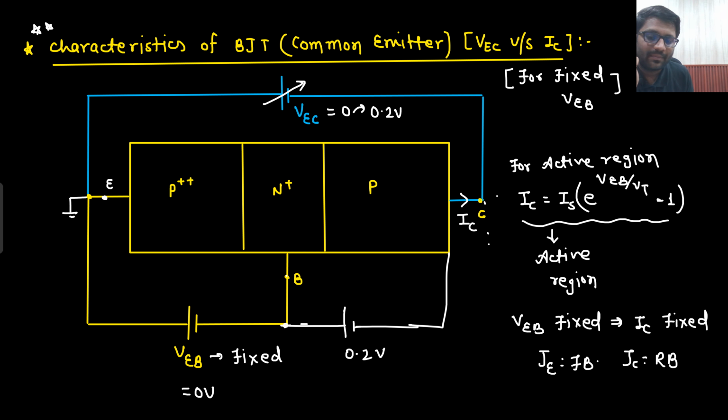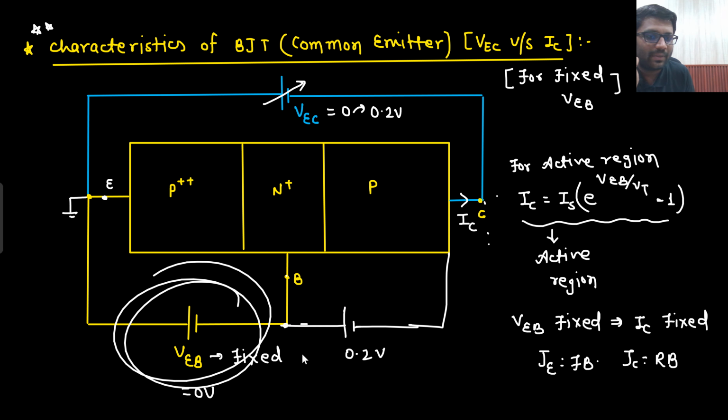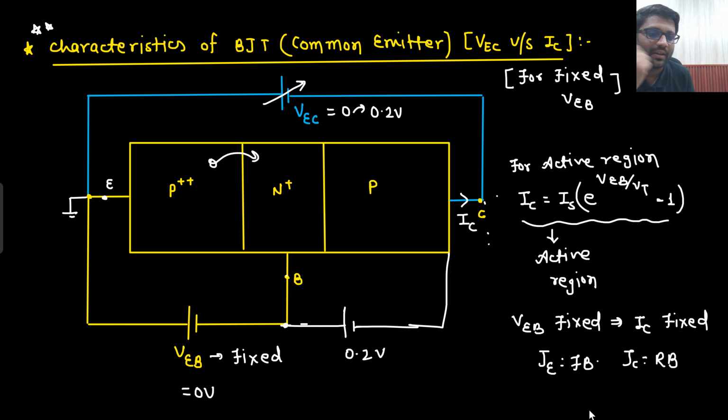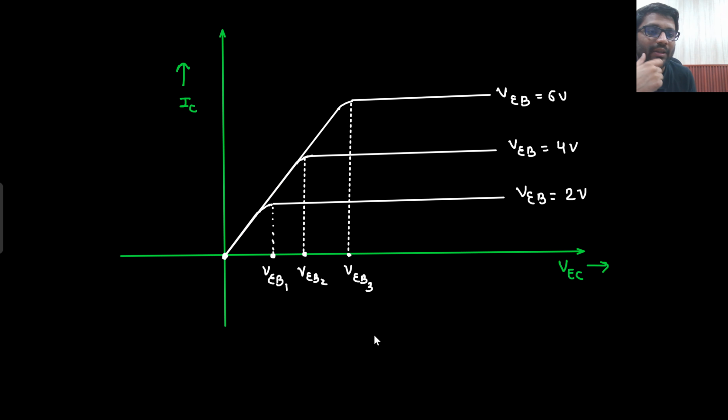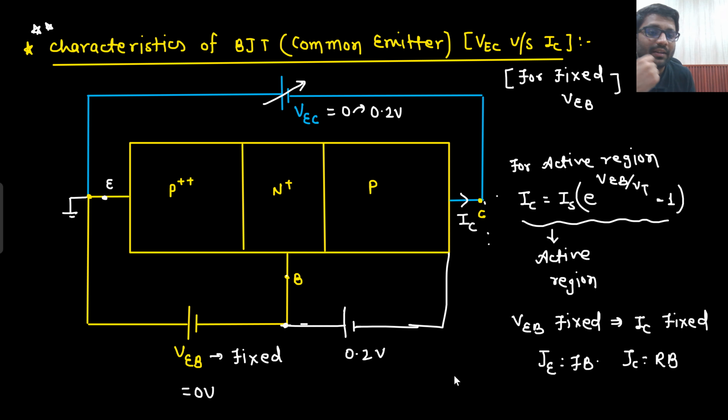Effectively this circuit has become your PN junction under reverse bias, because here there is no bias. That means no holes are coming from here to here. So whatever reverse bias you apply here, because of that reverse bias, some current would flow. But what would that current be? That current would be nothing but IC, emitter is open circuited, no? This current would be nothing but ICBO.